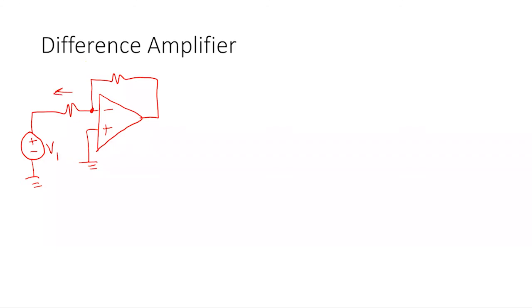And I talked about this when I first talked about nodal, right? Basically, if you do it this way, what you say is, all right, the actual current in this branch may be the opposite direction of what I drew here. Every time you write your KCL, you're making the assumption that all the voltages have that polarity. The reason I never like this is if I have this set up, let's put a resistor here.